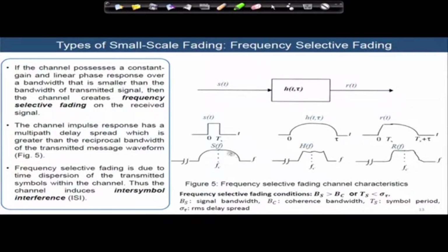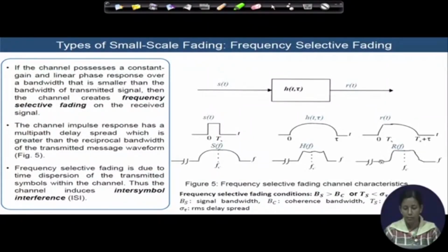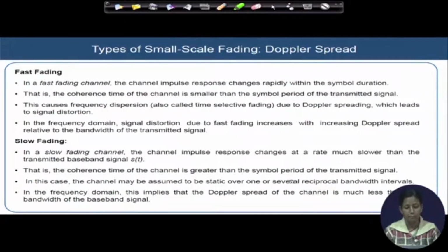The frequency components themselves will be partially present and partially not, and different kinds of amplitude reduction and phase changes are happening over the incoming signal. We call it frequency selective fading. See, the portion of the transmitted signal here in this zone has completely different amplitude changes compared to where the channel is really present. We call it frequency selective fading.